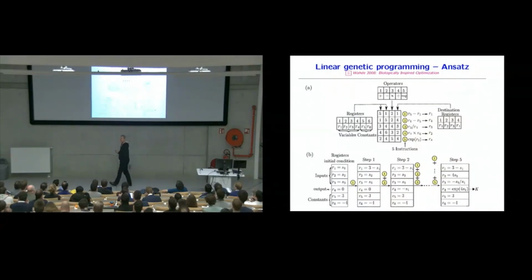And of course, it works also if you have 2 actuation inputs, 3 actuation inputs, and so on. Do you feel comfortable with that? To some extent, it's very simple. If I tell you the controller is a finite number of operations, which translates your sensor signal into your actuation command. The peculiarity here is that things are discretized in terms of a matrix. So you have an integer matrix. Now, what is a bit funny here is you have a finite number of control laws now,